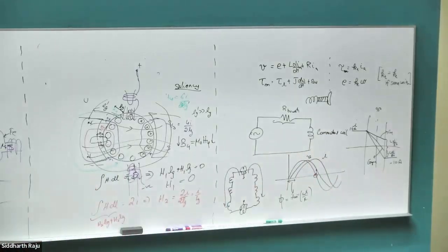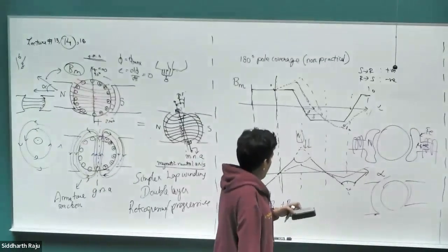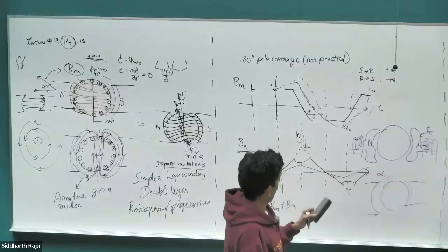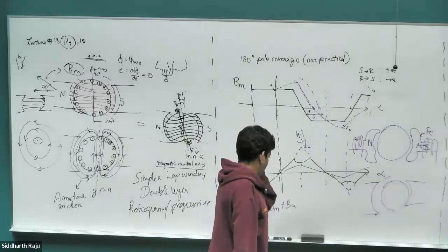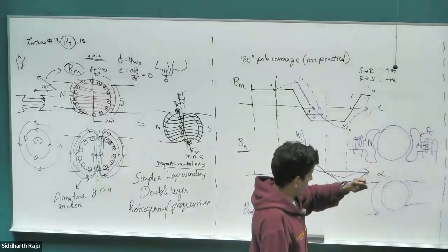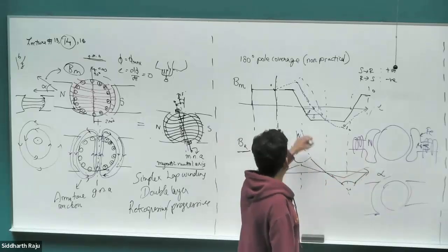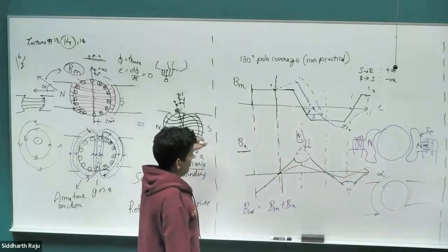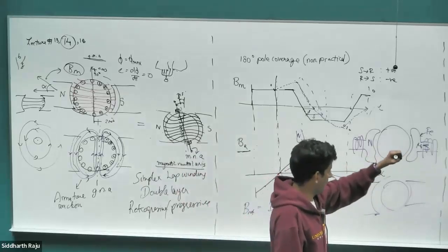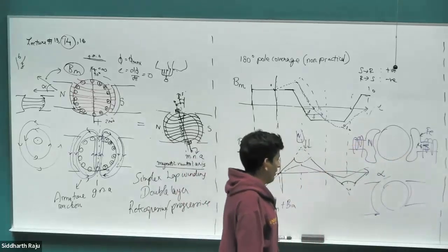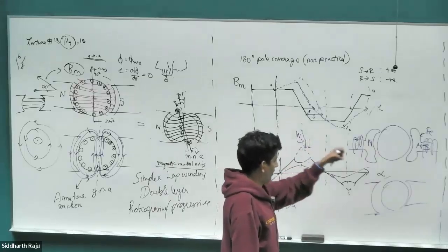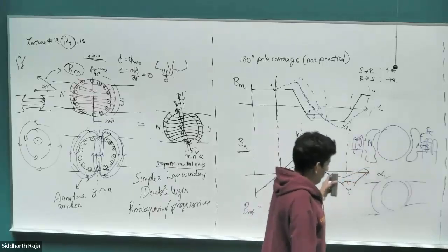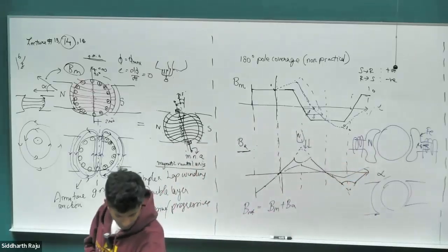Right. So let's go back to our drawing here. I did lose my train of thought for a minute. Okay, so the thing is, depending on the increasing of the resistance of the brush, we can reduce our armature L di/dt term, thereby reducing the arcing that we have. And so the other option is we can use the interpole, we can use saliency, and there's one more option that we have called compensation windings.